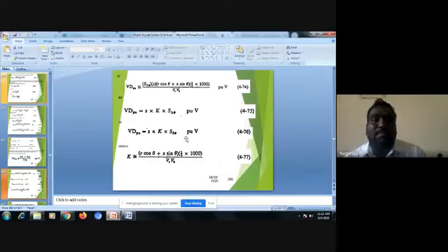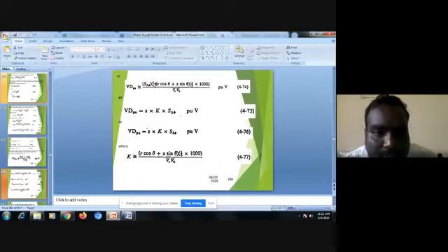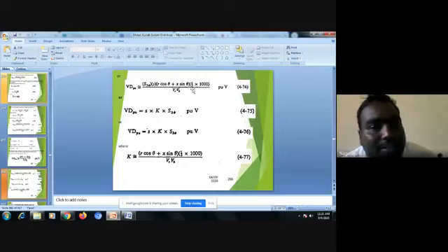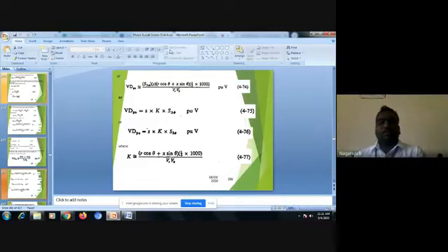For the three phase in per unit value, you will get 1/3. So S three phase into (R cos theta plus X sin theta) into 1/3, divided by the receiving end voltage and base voltage. Okay, this is about the calculation. So voltage drop per unit is equal to the apparent power of the three phase into K. This is about the basic formula.